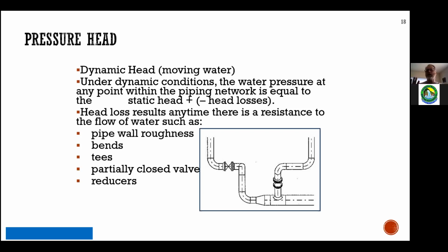So imagine a 2-inch water line crossing a road to a business, and then switching that out with a 1/2-inch line. Same distance, same business, same elevation, a lot less energy, not the amount of water, but if you put a pressure gauge at the house or the business, it will be different based on head loss. So head loss is really critical. We have to manage that when we're designing and operating our water systems.